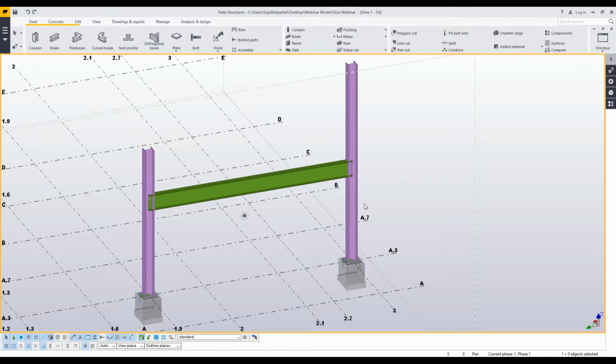I want to start by giving some basic information about how Giza can interact with Tekla. Using Giza, you can grab connections from your Tekla model, run all of the calculations, design the connection, and then put the newly designed connection back into the Tekla model. Currently, we support Tekla Structures versions 18 to 2017, along with 129 different connection configurations, including shear, moment, and vertical brace connections. Our list of supported connections is constantly growing as we continue to add connections that our users need.